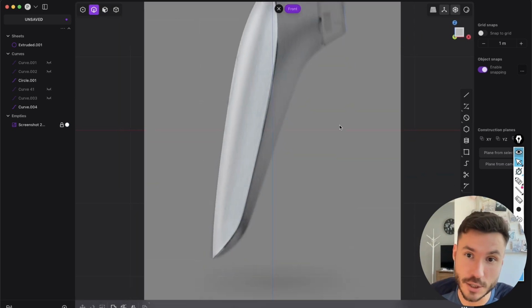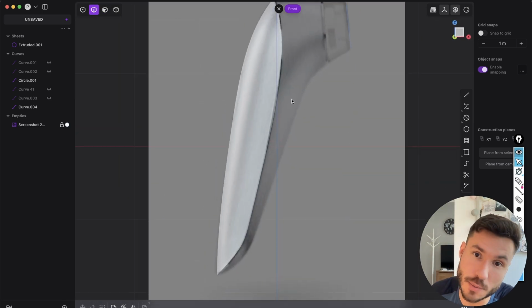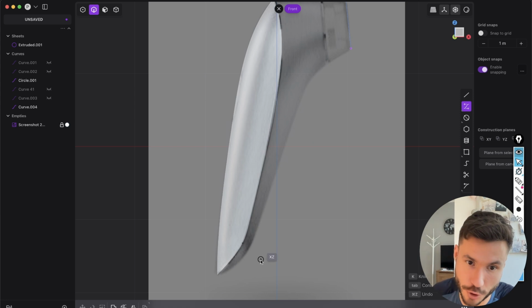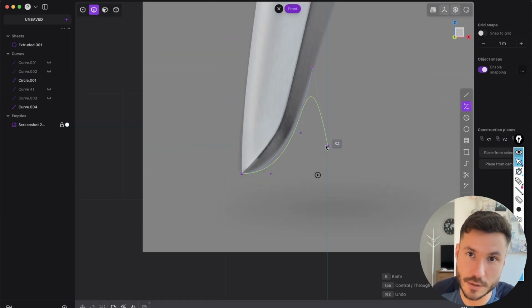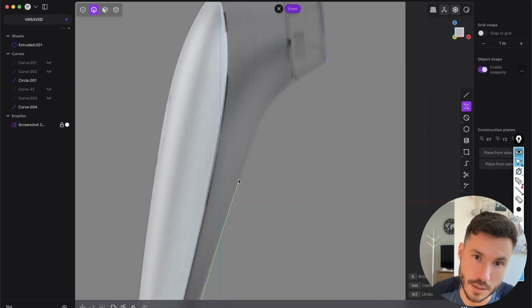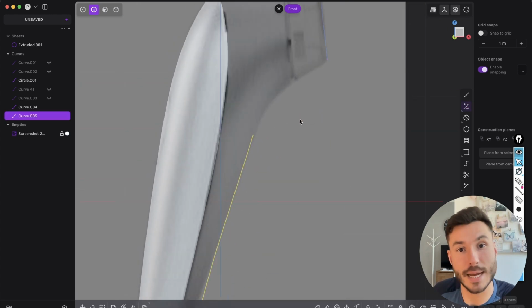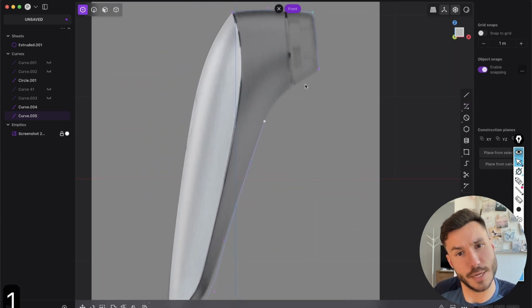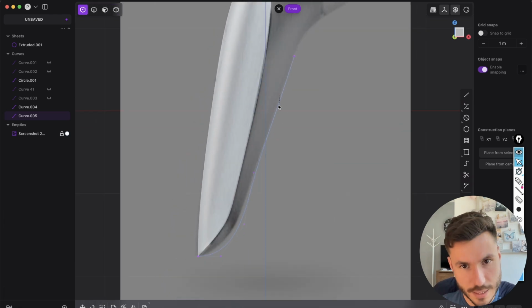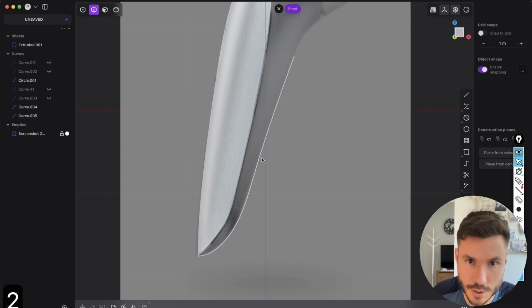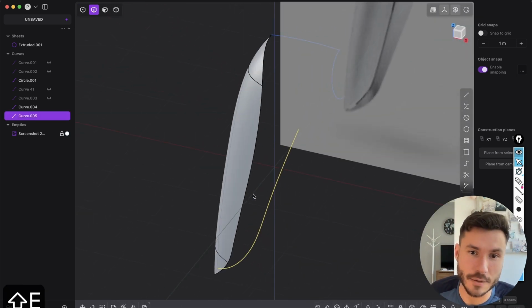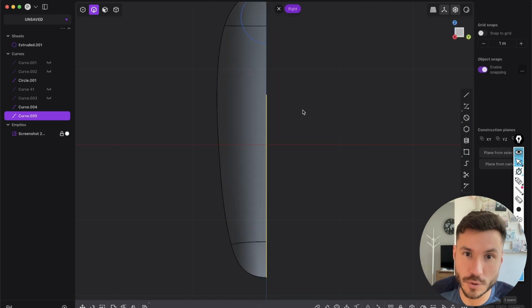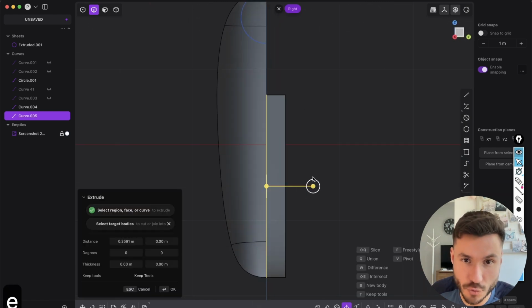And what I just told you, we will go to this point first. Again, control point curve, go here to the end and create a few points and just follow that shape till somewhere here, maybe somewhere here. That should work fine. And again, just a few points. Spend some time and love to adjust them, but that's fine for me, right? And again, we will go to the right view and press E and extrude that.